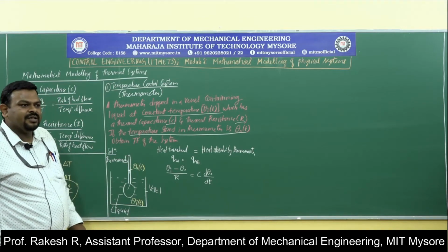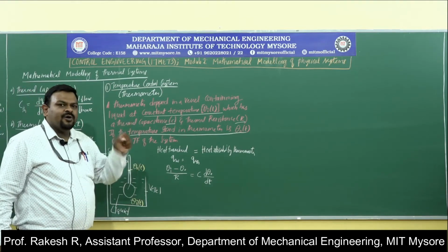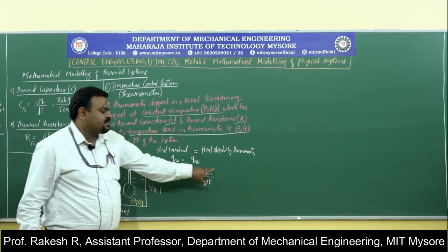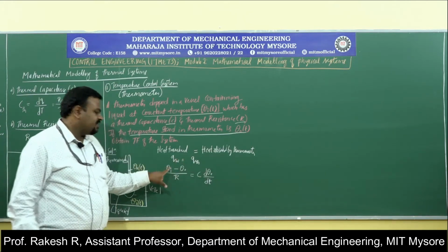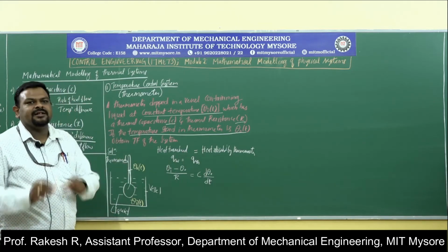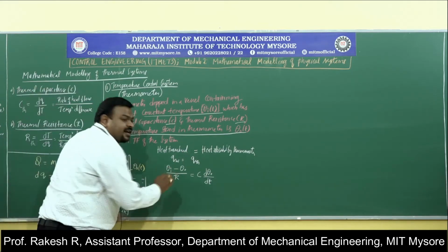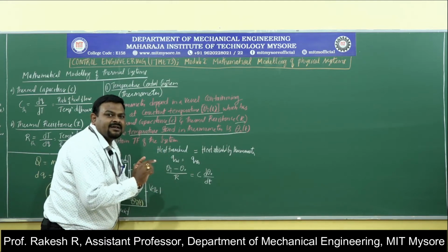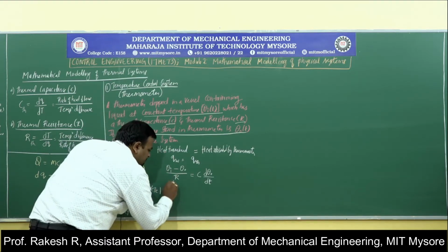Now we need to know which is the output and which is the input. The output is theta naught. The input is theta I. So we need to write the expression. Before that, I need to change the differential equation to the Laplace domain, so apply Laplace transformation.